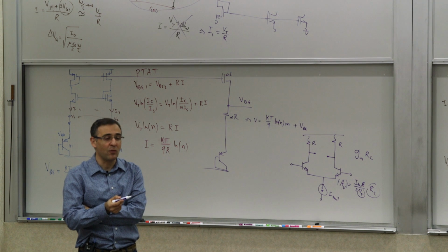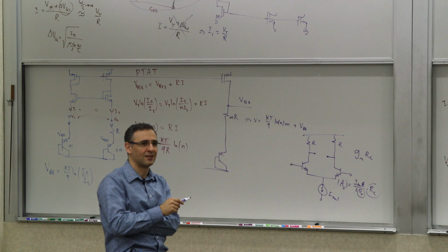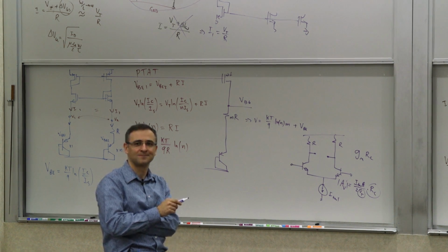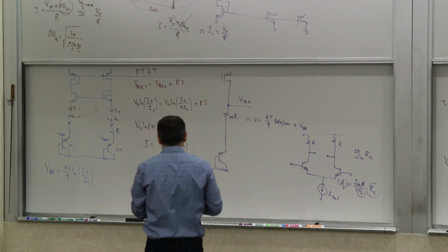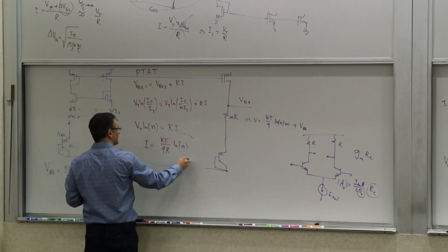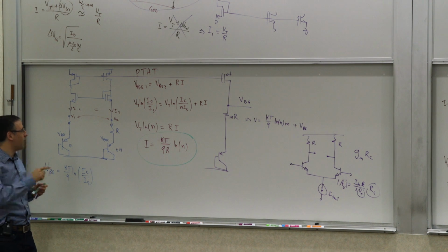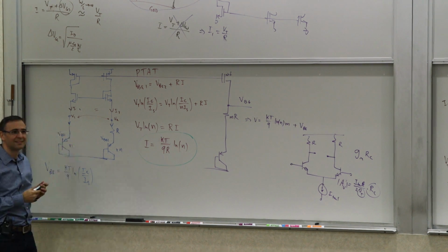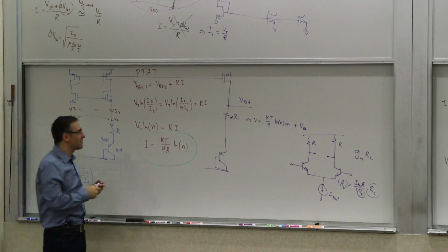So in fact, if I want to keep the gain constant, I don't want a constant current source. What do we want? Proportional to temperature and inversely proportional to the resistor, right? Do we have such a thing? Have we already created one? So if I bias it with this guy, I would probably get the right results, right?